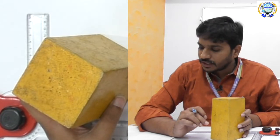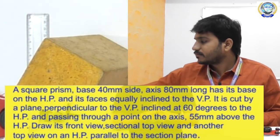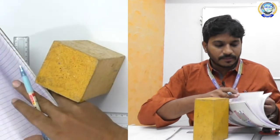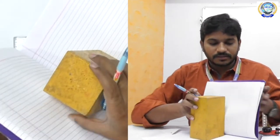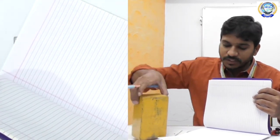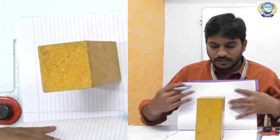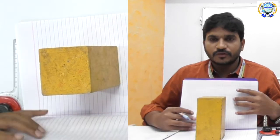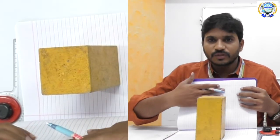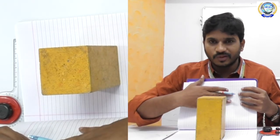In the question, it is given that its faces are equally inclined to the VP. This is the vertical plane, and this is the horizontal plane. The object is placed like this. This is the starting position of the object. The faces are now parallel to the VP. This face is parallel to the VP, and the back side face is also parallel to the VP.